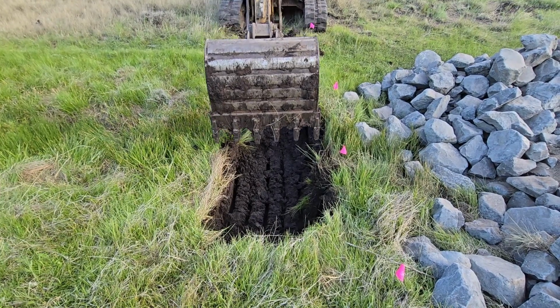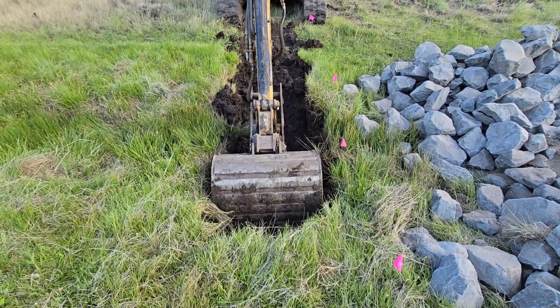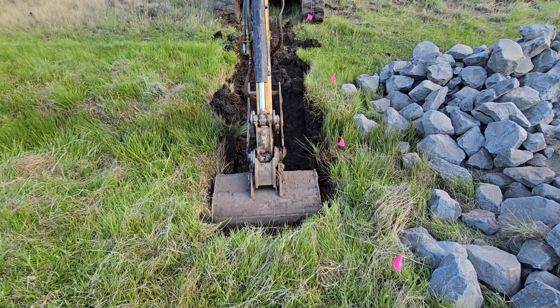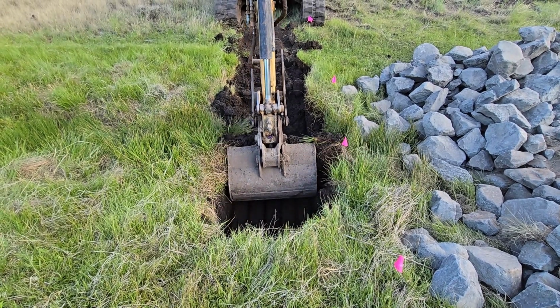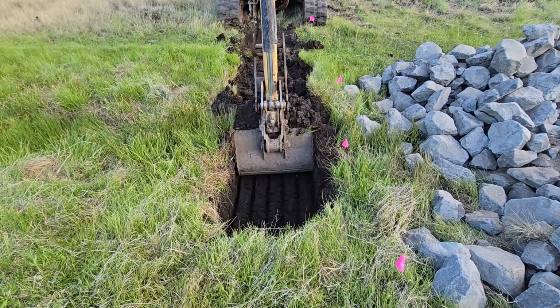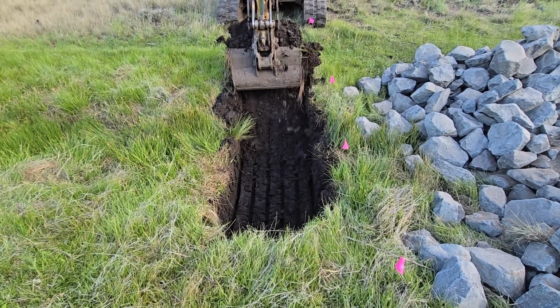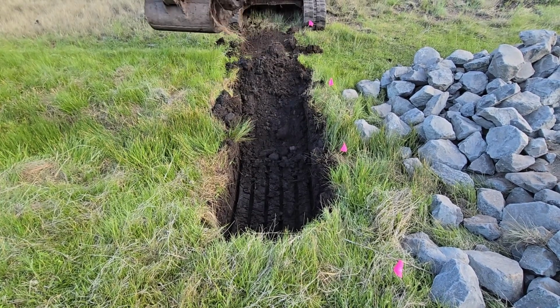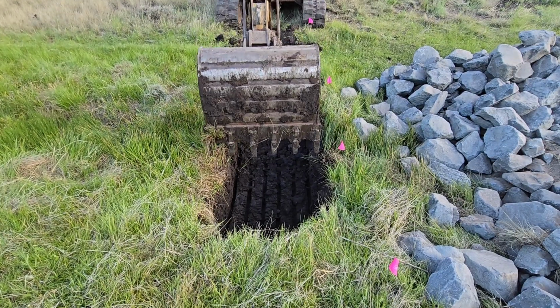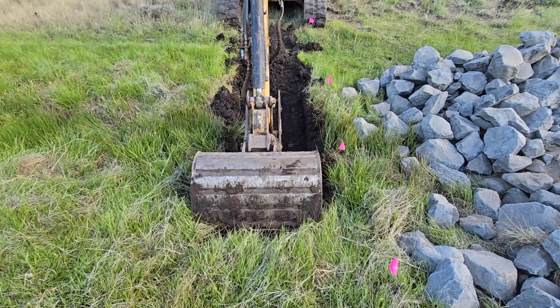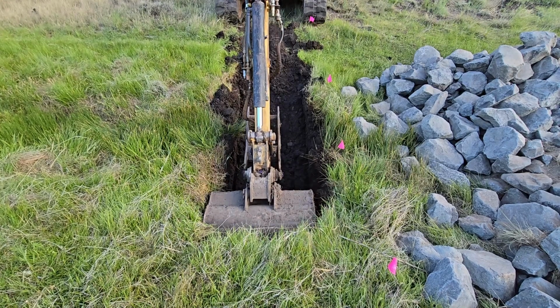The purpose of the core trench is to interrupt permeable layers of soil, replacing this permeable material with soil that is high in clay and compacted in layers. The trench begins at one side of the valley at an elevation that is equal to or higher than the estimated water level in a 100-year flood. The trench is dug through vegetation, organic soil, and the compacted clay near the surface.